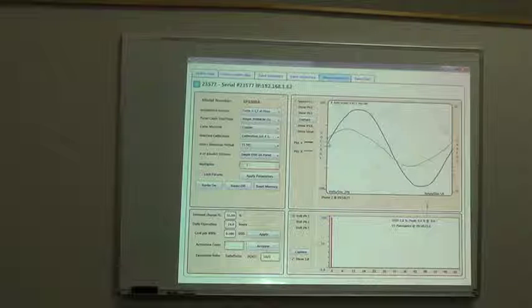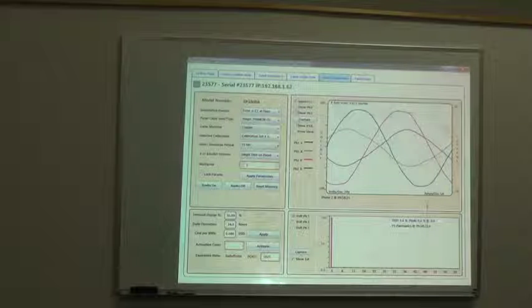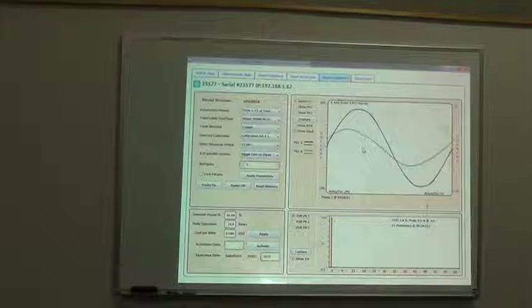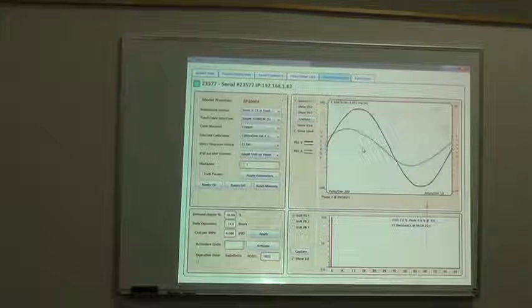But in any case, that's where the majority of the benefit comes from. So I have added a couple of functions over here. One of them is the show ideal, and what it shows you is basically the ideal curve for that power factor for the phase, for the current and the voltage, mathematically. What it does is generate an artificial AC signal with the same amplitude as your actual consumption. And then it says, okay, let me match them, find out where is the minimum error between the actual one, in the same phase.